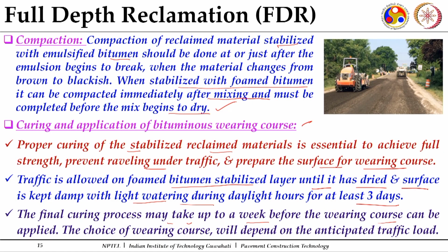The choice of wearing course will depend upon the anticipated traffic load. It may be a bituminous concrete or a stone matrix asphalt, depending upon your traffic load. So, this is all for this talk, where we discussed cold in-place recycling, cold in-plant recycling and full depth reclamation. In the next talk we will discuss the mix design aspects of cold asphalt recycling.